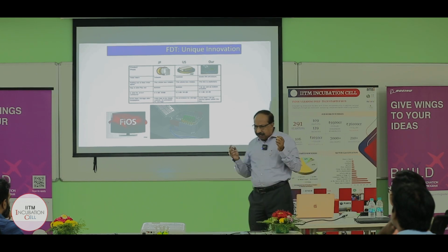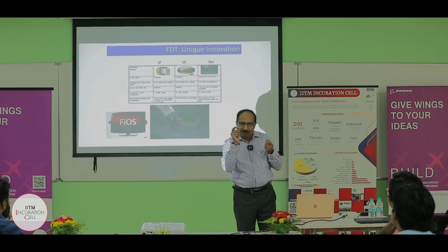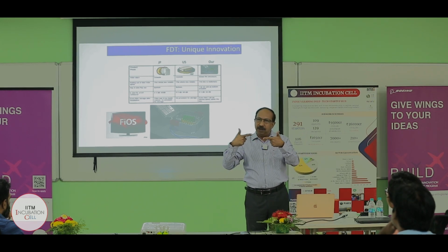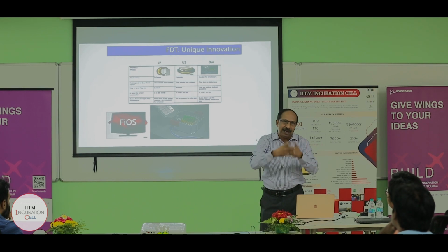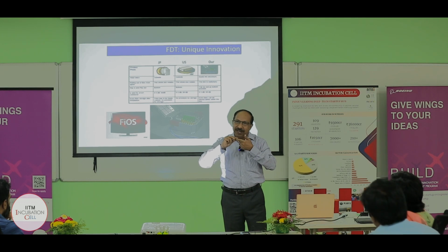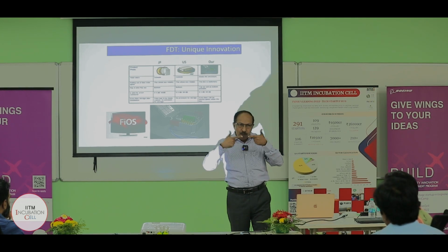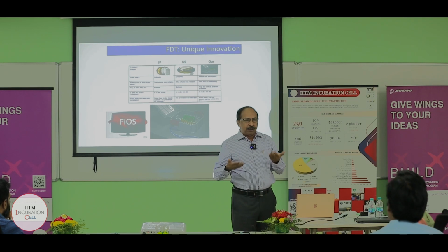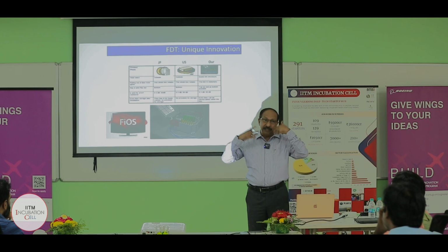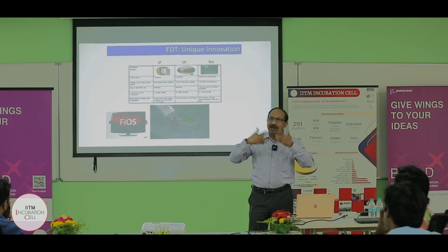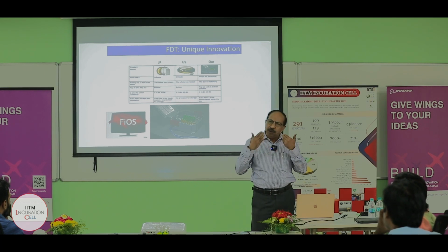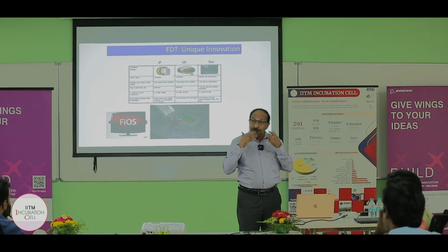The idea here, I will be focusing more on the fiber, because that was one of my favorite areas. When you want to connect fiber, you cannot just connect or twist like the copper one. You have to align properly, you have to fuse it. Otherwise you have to put a connector. Fusing is better because loss is less, so they always preferred fusing. But when you want to do fusing, a technician has to go there, put the fiber, fuse and all. It takes a lot of time and manpower. So they were asking us, can you come up with a solution which will save this manpower?